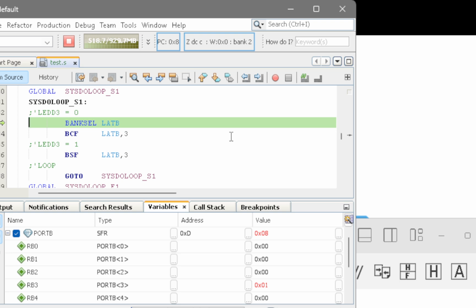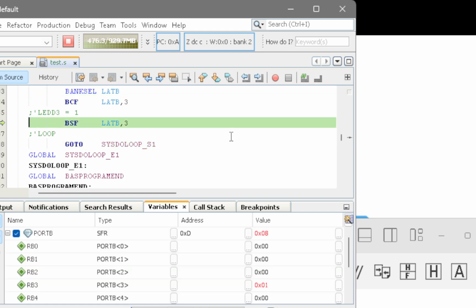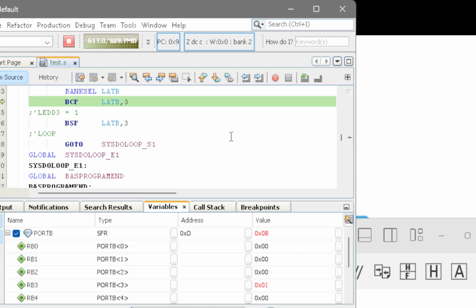It's logical to have it inside because if you had a call to something different in a more complex program, we're talking of one word. So we're now seeing function key F7, we're seeing the compiler in GCBASIC within MPLAB-X, and it's doing its stuff. Yes, you can do a lot more complicated debugging in here, but I'd also be using serial and I'd stay out of MPLAB-X, but you can do it. There is rationale for using this, and you can do the same with AVRs, the same with LGTs, same with newer chips as well. It's a very good capability.